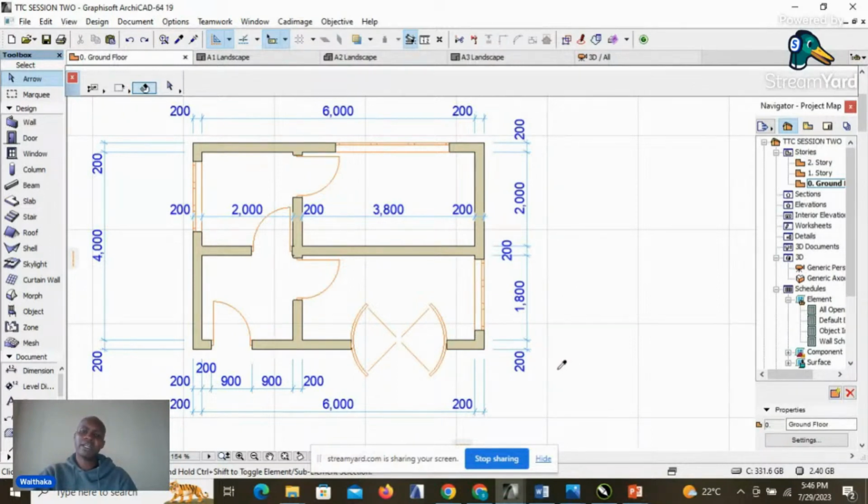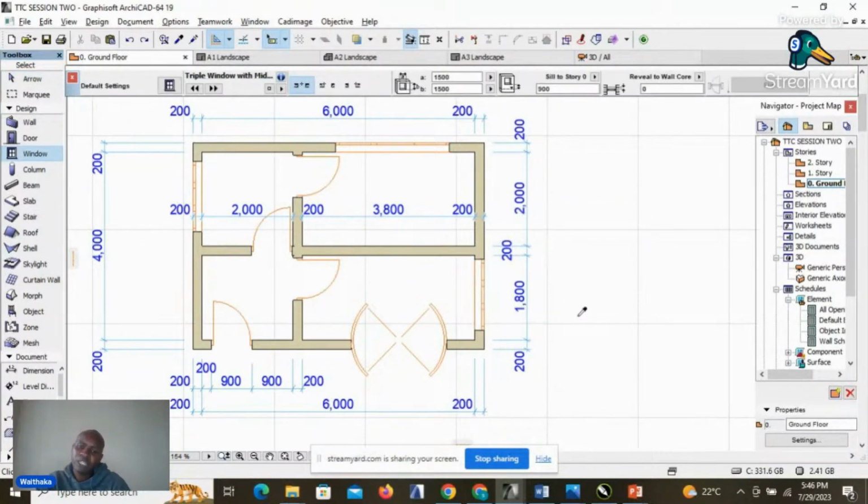If you press the Alt key on your keyboard, you'll see that your cursor changes to the pick parameter tool. Once you release the Alt key, it will disengage the cursor. Once you hold it, it will maintain the pick parameter tool. So we press the Alt key, hover over the window that we want to pick parameters from, and click on that window. Then, before we release the Alt key, we add Control. We hold the Control key down, and it will change the pick parameter cursor to inject, and then we can inject the window that we wanted to change the parameters of.